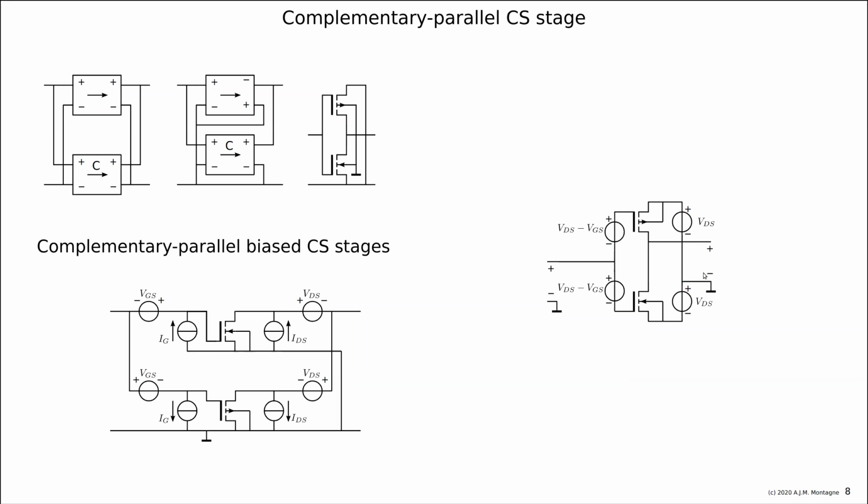So then you get this circuit, and now you see a positive and a negative power supply, and the voltage VGS was minus because you look at the orientation, yes, because we now have the source drawn on top of the P device, and of the N device we have it on the bottom. And so we have to shift VDS to it, so we obtain VDS minus VGS as bias sources here.